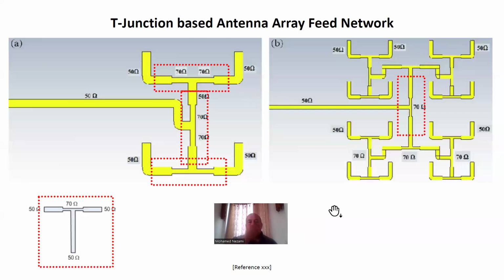All right, so next, let's look at this. This is another example that I grabbed. He started with this first, okay, which uses basically this here. So you got 50 ohms and separated by 70 ohm and then 50 ohm. So they have it here, and since this is 50 on this side, again, now you go from 50 to 250 splits, and you use exactly the same one. So they repeated, this same transformer is used here, is used here, is used here also, which simplifies the antenna array feed network because all you have is just a single one.